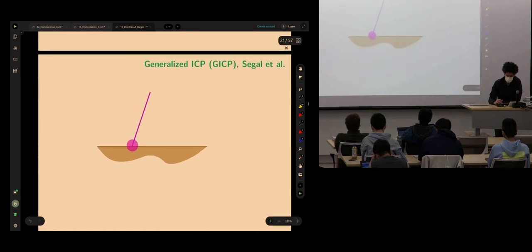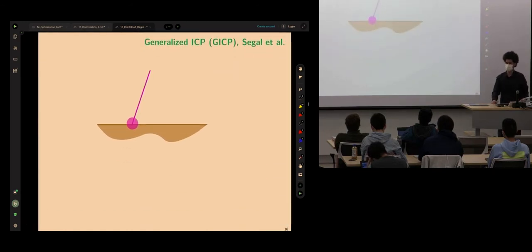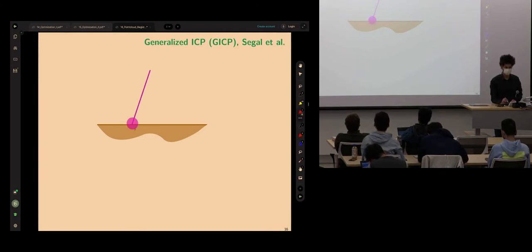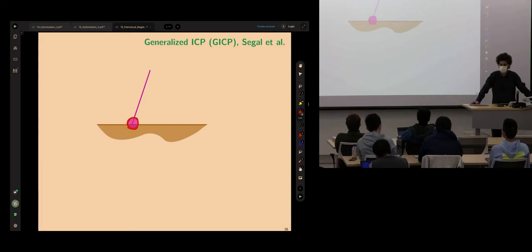So we want to work with a probabilistic model. Consider each range measurement from your point cloud to be noisy. Assume a tiny covariance for that point. For example, if the Lidar is good, you might get a standard deviation of 5 centimeters, something like that. A stereo camera is going to be very large. The farther you go, the point clouds can make a wave that makes everything distorted.